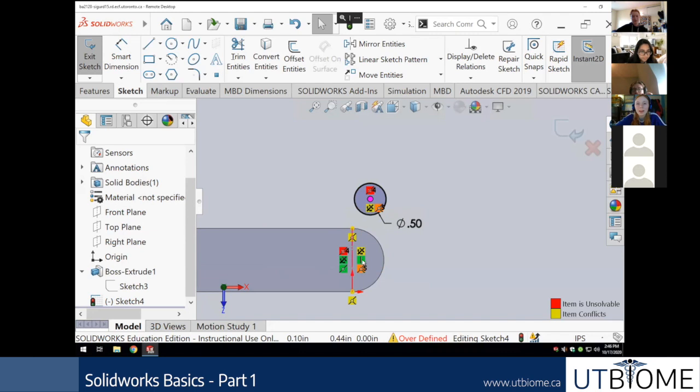So there are anchors. I haven't explicitly said this yet, but we never use the anchor. The anchor is what unprofessional engineers use. I'm not saying you're an unprofessional engineer. I'm saying you accidentally clicked the anchor. The anchor tool is called the fix tool, and it has caused a lot of problems here because it just says, I have no clue what the dimensions are, I like how this looks, force it to stay here forever.